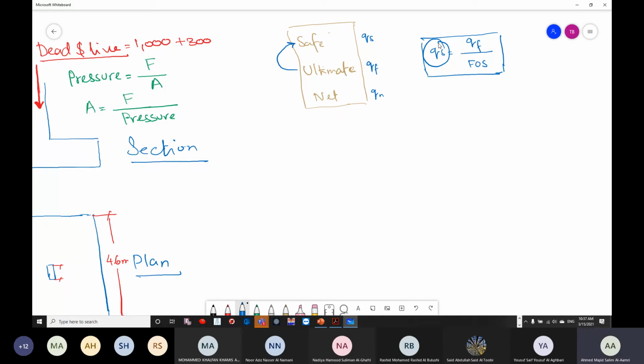So one factor of safety has already been applied when it comes to the soil. No need to take another factor of safety. That's why they call this a service limit state condition. We don't multiply by a factor of safety. Are we okay now, Wadha?